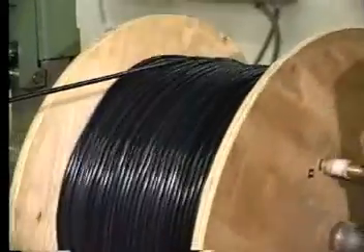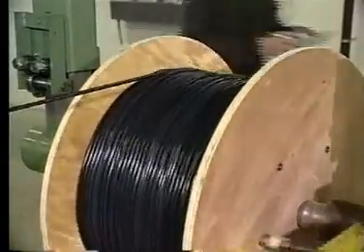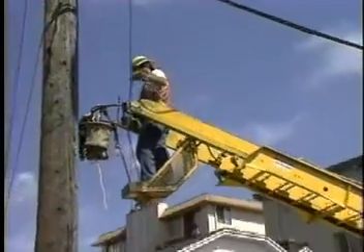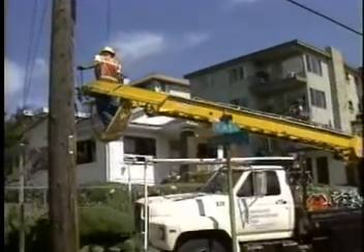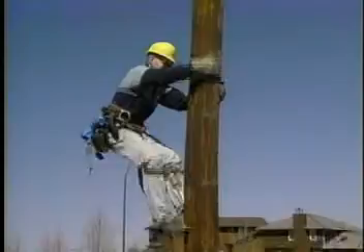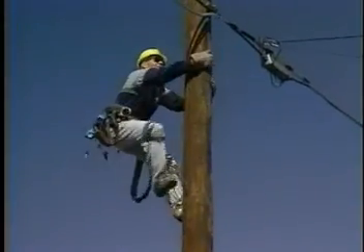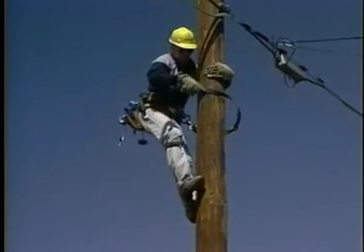Clean, dry cable has the highest surface resistance, while wet cable can reduce resistance by up to 60%. For this reason, never install cable on active towers during wet weather. Whatever type of installation method is chosen, safety must always be your top priority. Be sure to follow the guidelines laid out in all pertinent construction and safety codes.